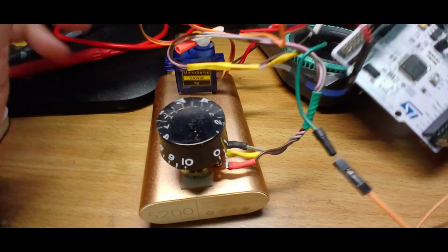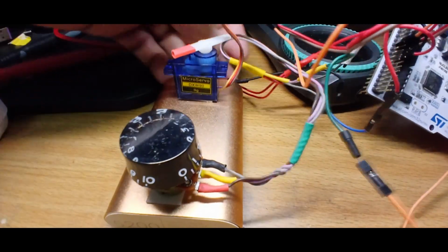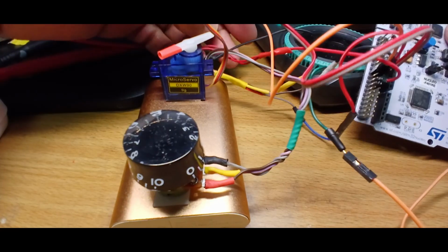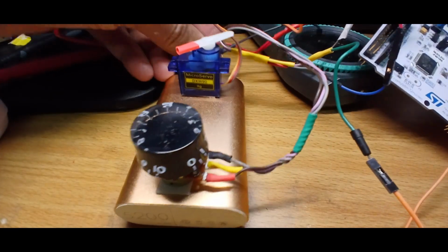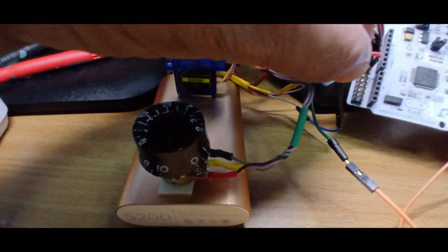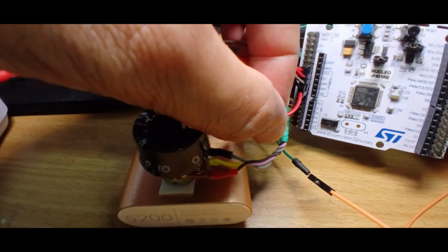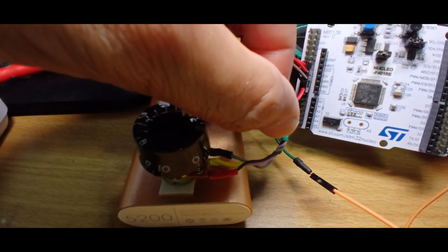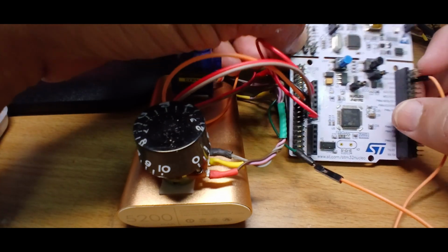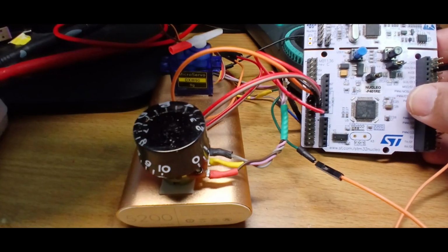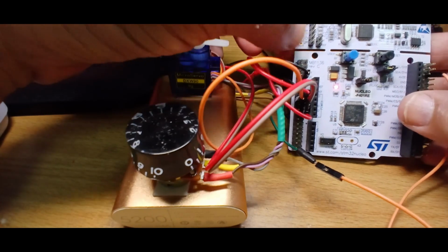Now one more thing, I connect this full system after flashing the code, with a 5 volt supply from the power bank. I connect here, which is called the VIN pin. You can see here the VIN pin, that is for the external power supply. Okay, when you power from an external source, first is the VIN pin, second is the ground pin. To the ground you have to connect, then the board light is up.